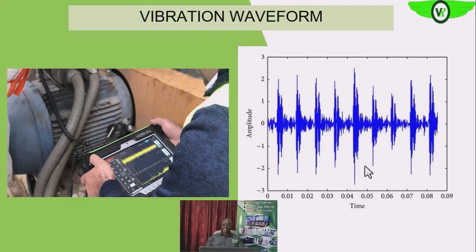Are you getting it? And this pattern, this increased vibration, if you also look critically, you will see that they are occurring at regular intervals. That will give you a sense that something is happening at these intervals. It could be in pattern, especially if these intervals coincide with one-times RPM. Are we getting it? So that is the beauty. But what is actually causing this vibration?